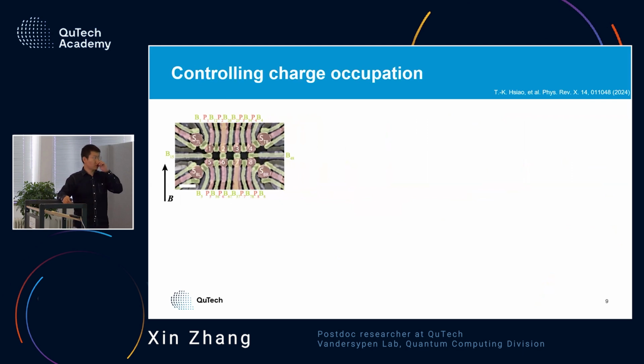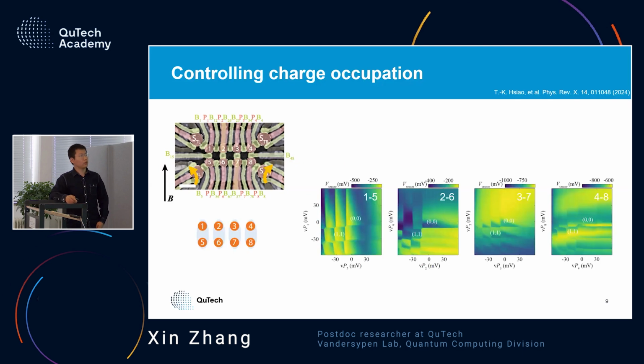The first thing we want to characterize for this device is to measure the charge states in the quantum dots. In this device, we use the bottom 2 sensors to sense the whole array. This is the result from changing the gate voltages. We can form 4 double quantum dot pairs along the rungs of the ladder. You can see we can totally empty the quantum dots to (0,0). And we can also confine them to 1 electron per dot. Actually, here it's a hole because it is germanium.